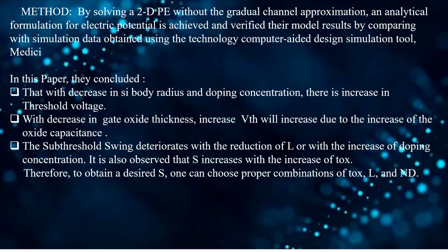We know that junctionless transistors work in the partially depleted region. As silicon radius or doping concentration reduces, the total number of electrons from the ionized donors in the channel will also reduce, and a larger gate voltage is now needed to deplete the channel less, so more electrons are left in the channel to turn on the device.